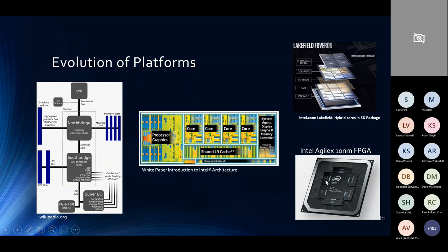You have some transceiver blocks at this platform level, and you are connecting these through that EMIB structure at different dimensions. So at a platform level, these individual chiplets, if you will, can be fabricated using different process nodes, but you could integrate them at this platform level with the help of this EMIB structure.